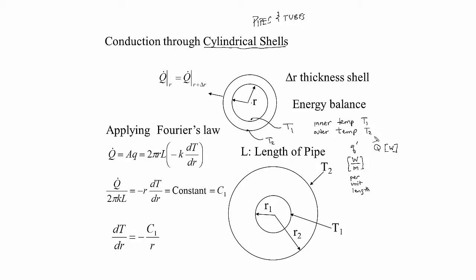We'll certainly use Fourier's law and an energy balance, but just to think about this energy balance a little bit, let's imagine a situation where, for some length of pipe, we have 100 watts being dissipated through that pipe from the inside. So we have put some sort of resistive heater inside this fluid and caused the fluid to transfer 100 watts to the inside layer of the pipe.